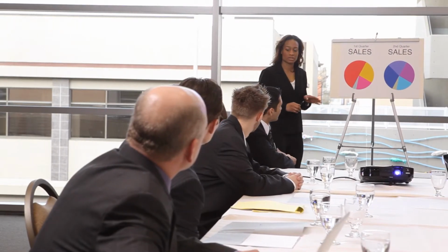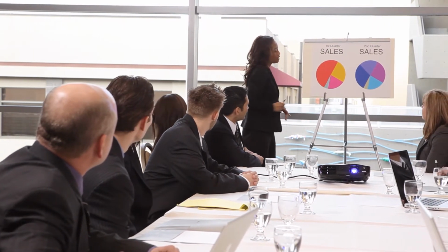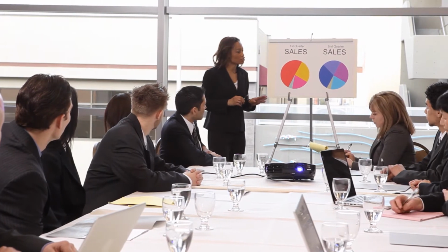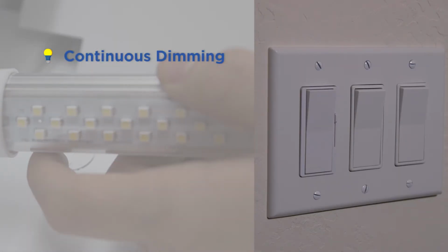In practice, this can be achieved in a couple ways. Continuous dimming: a manual dimmer controls all general lighting in the conference room. In this case, continuous dimming ballasts or drivers are needed for each luminaire.